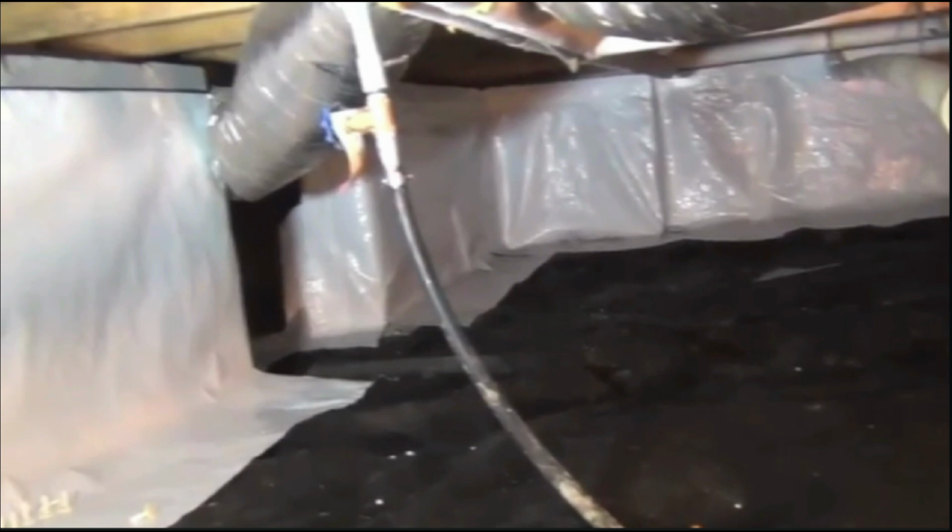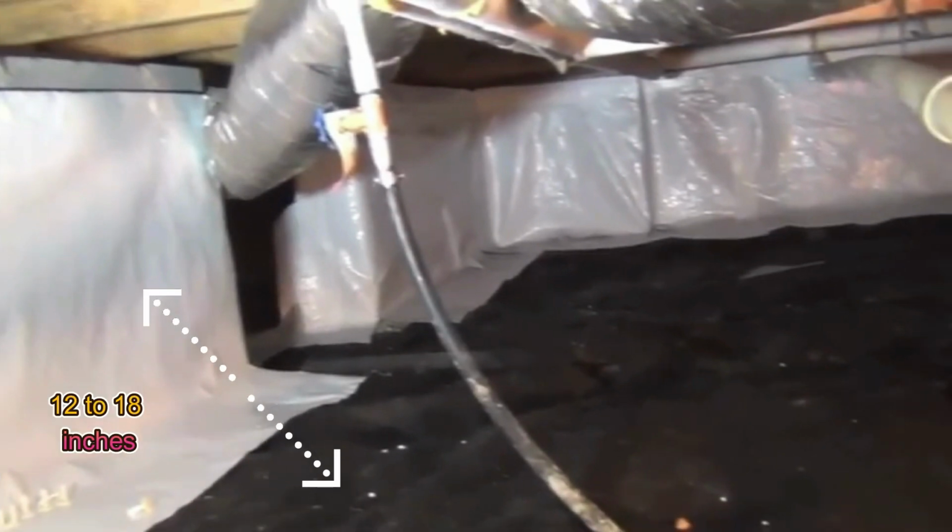Once we have our sections of vapor barrier underneath, we attach them to the double-sided tape. You can see here that we have several inches of extra barrier extending out into the crawl space floor. This is so we can overlap the floor barrier up on the walls. This makes seaming the two together much easier. You would never want to try to tape two sections together with them barely meeting. You need an overlap of 12 to 18 inches.